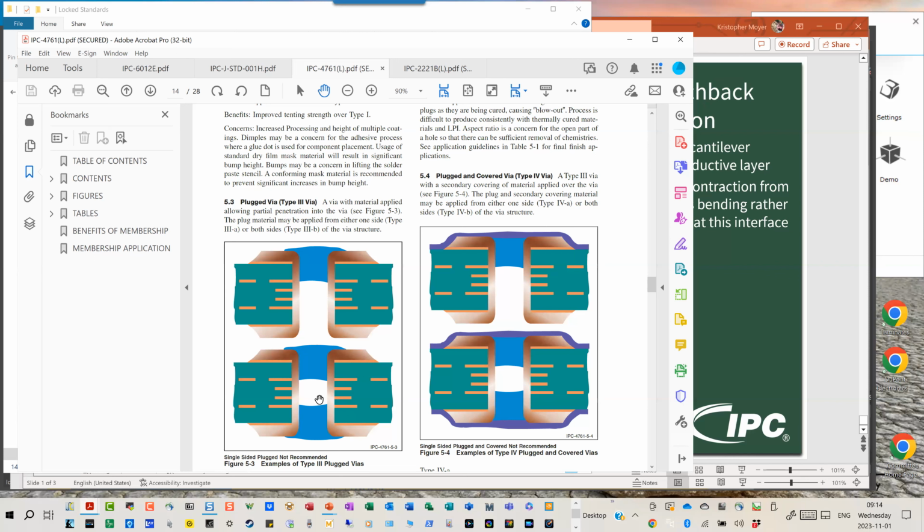One-sided, okay. Two-sided, even if it will not decompress vertically through the barrel wall here, anytime I have a void like this where I can entrap moisture or other contaminants from the washing and cleaning processes like at the fabricators, if that pressure... I'm not completely ignoring that pressure, but what happens is if that pressure cannot decompress vertically through the barrel wall, it will go horizontally. This is where we start seeing those barrel wall cracks.